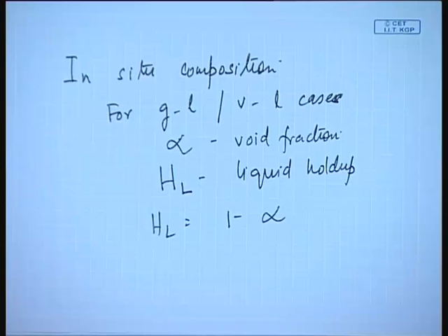Okay. Very frequently we would prefer to use liquid hold up instead of void fraction to specify the composition of the two phases. Why? Because suppose we have a liquid solid flow, we can use HL to specify the liquid hold up. If we have a liquid liquid flow, we can use HL to specify the hold up or the fraction of the heavier liquid there.